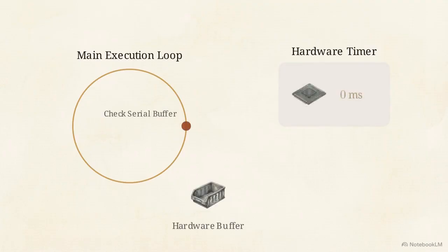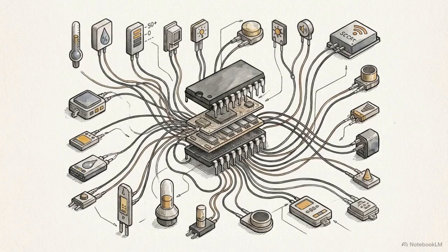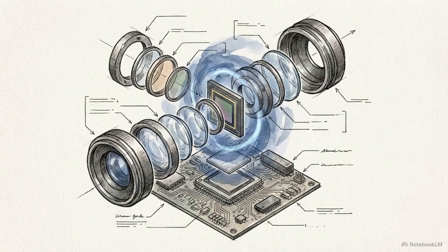Instead of halting the processor, the Compass methodology tracks time using independent hardware timers, internal registers that tick away regardless of what the CPU is doing. The main code runs in a continuous loop, quickly checking the time to see if an interval has passed. Every single incoming signal is caught the moment it arrives. By writing code that never stops to wait, the microcontroller transforms from a sequential task runner into a highly vigilant sentinel. It continuously monitors physical sensors and digital inputs without dropping a single critical command.